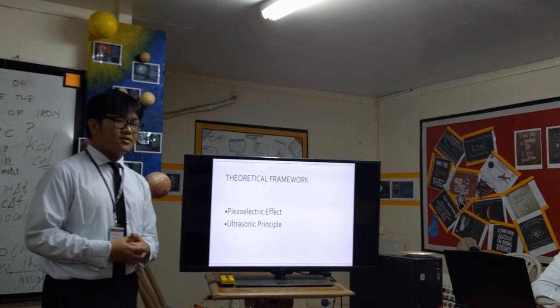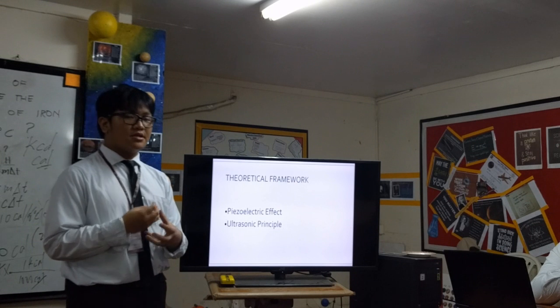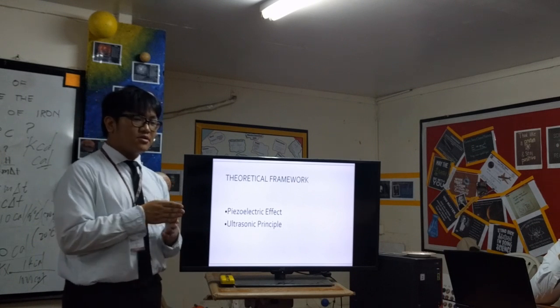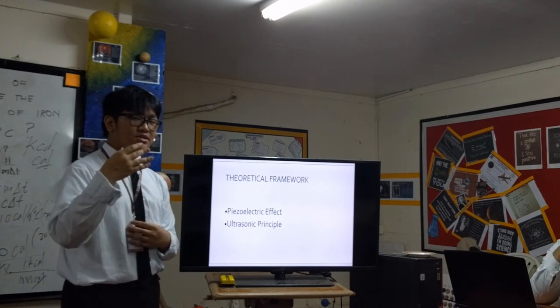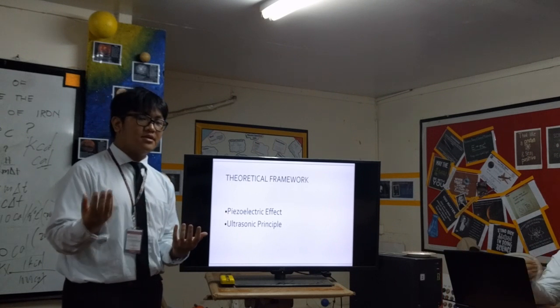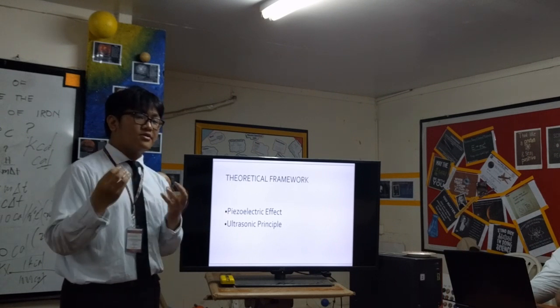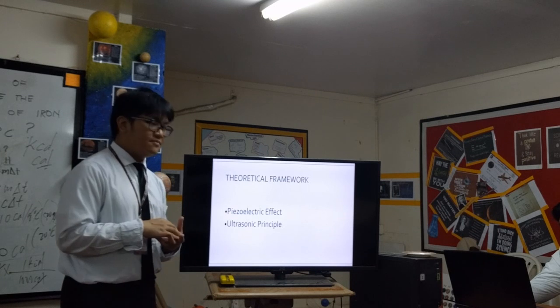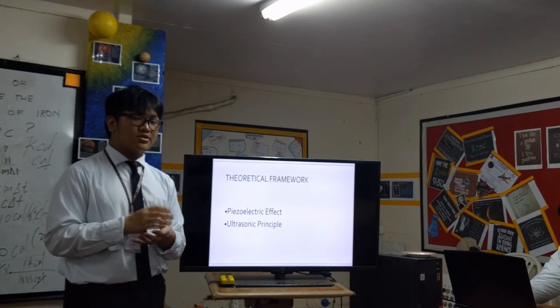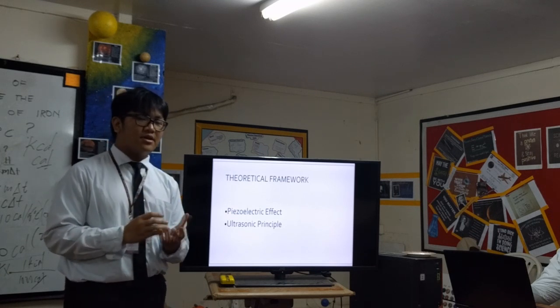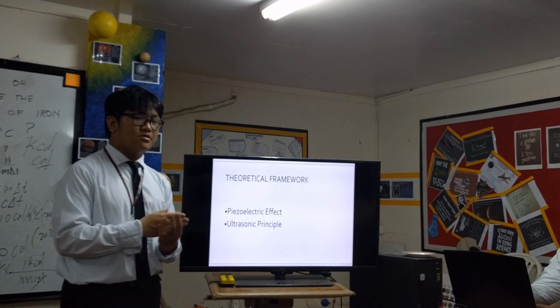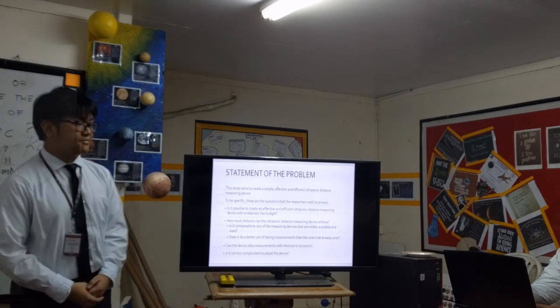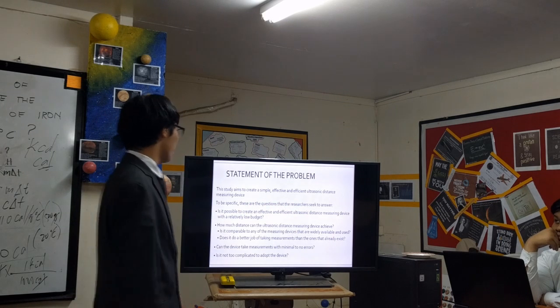For the ultrasonic principle, once these sound waves are emitted, they will go to a surface, and because they are sound waves, they will bounce off or echo, and the receiver will receive this echo. And this is how the sensor, or the device as a whole, will measure the distance from the device to the object.